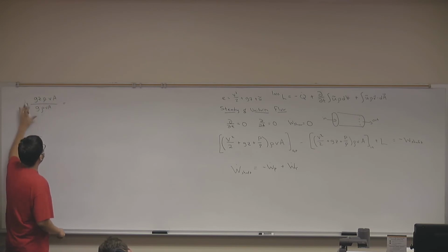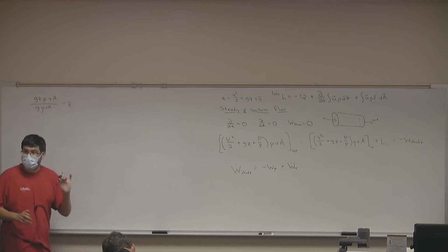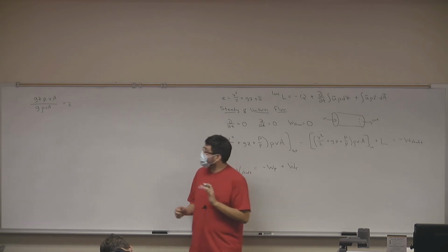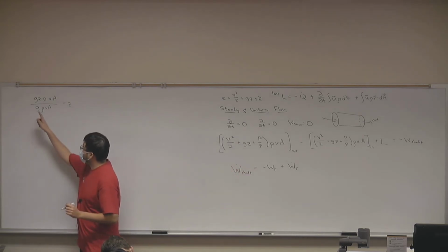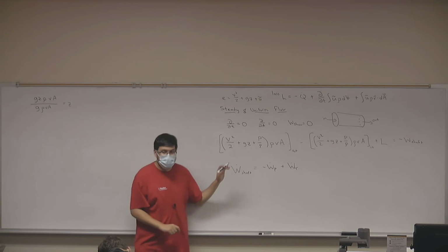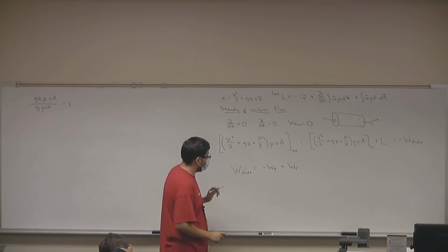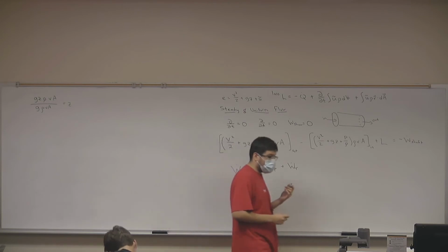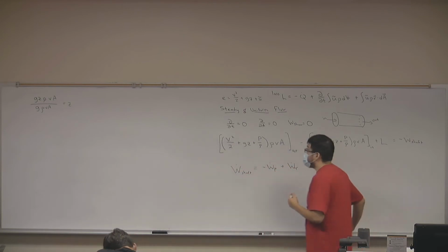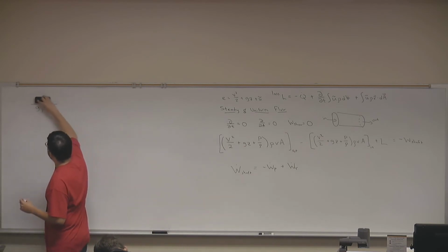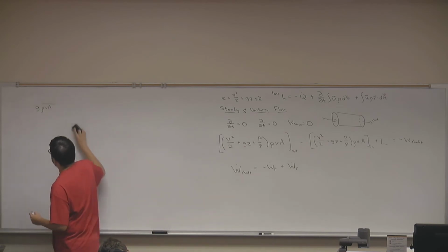Okay. So if I divide all of this by gravity, density, velocity, and area, you're saying that I get a length. Is that correct? Because of dimensional homogeneity, if I divide all of those terms by gravity, density, velocity, and area, I should get all of my terms expressed in lengths, because the equation is dimensionally homogeneous. So that is what I would like to do. I'm going to take all of my terms and divide them by gravity, density, velocity, and area.